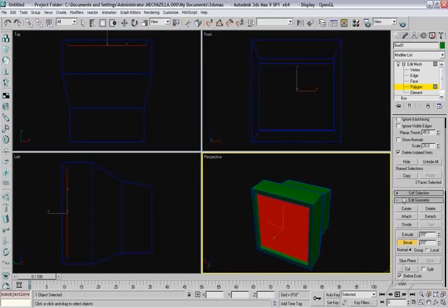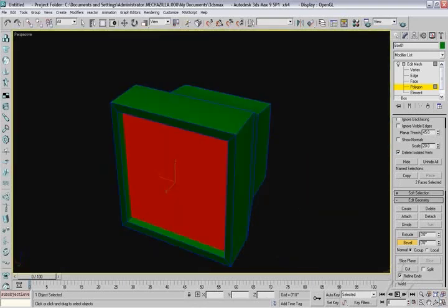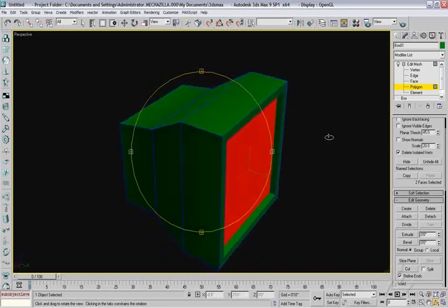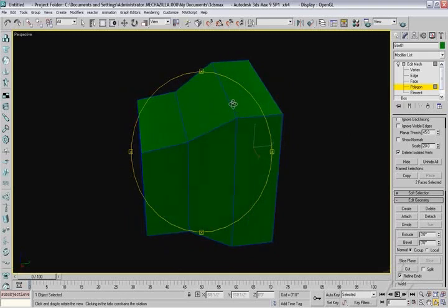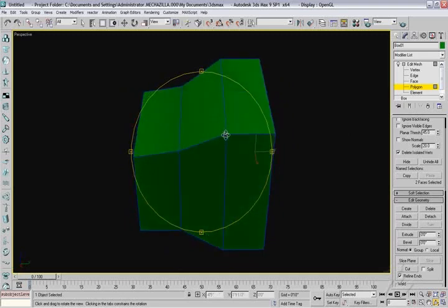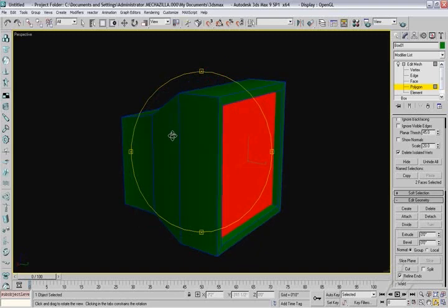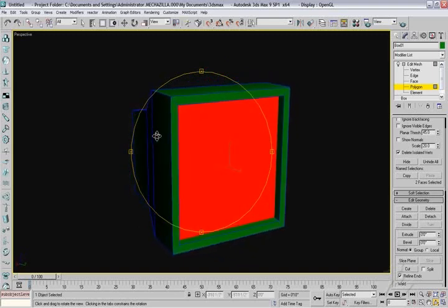There are some other things we need to consider when we work on our geometry. If we go ahead and maximize the perspective view, we can observe our model. Typically when we inspect our models and do what's called optimizing or cleanup, we go into the perspective view and rotate around and look for errant things or issues that we may have to clean up. For example, this would be the stage where we would clean up any extra vertices. As I said earlier, we actually had plans for these vertices. You can see how they support the geometry. So we need each one of these, and in that case it's very clean. We don't have to worry about getting rid of any extra vertices.